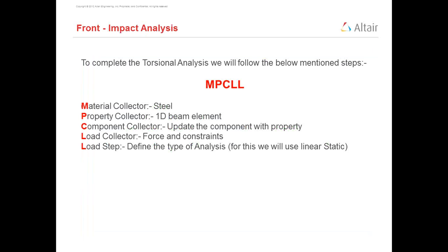For the torsional analysis we follow the same process as MPC, in which we will first create the material, then we create property by defining cross section through hyperbeam. Then we update the component which is created earlier by importing the model itself. Then we apply forces by creating load collector for forces, and then we create constraint and apply the constraint on my model. Then last step is to define the type of analysis by defining load step. For this type of analysis I am going to define the linear static analysis.